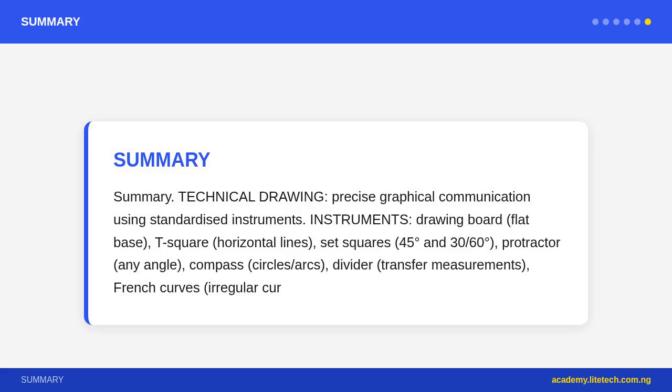Pencil grades: H, hard/light, for construction lines, 2H, 3H. B, soft/dark, for outlines, HB, B. HB, general/lettering. Paper sizes: A series, A4 the smallest common, to A0 the largest, each half of the previous. Cartridge paper equals standard drawing paper.